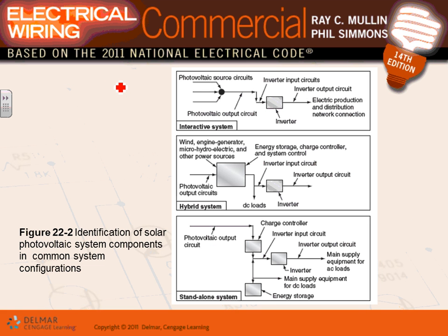Here's a good explanation for that one, guys. Here's all the strings coming, solar photovoltaic system. You bring them to the combiner, you combine them, you bring them to the inverter and invert them. Right here, guys, I want to do a couple of calculations. The way they size these conductors, they take 1.56, I believe, and they size the conductor based on the short circuit. 1.56 times I short circuit for the panel. So they take the current of the panel. Say this panel is 1 amp, and they multiply by 1.56.